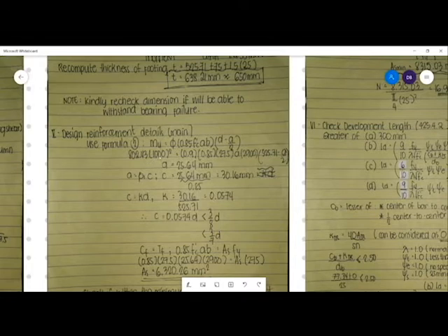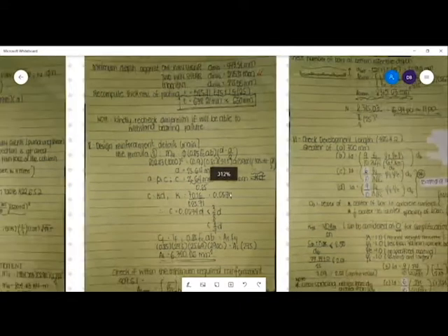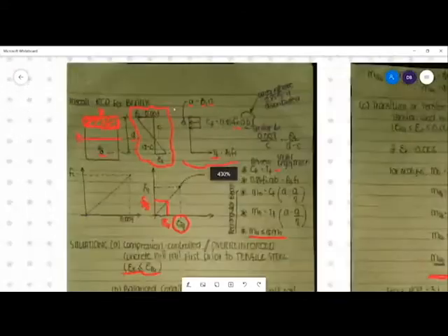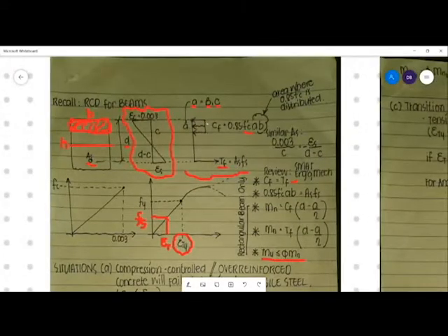We multiply it by 1,000, and another 1,000 to make it Newton millimeter. Then, equal to 0.9 multiplied by 0.85, 27.5 a, 2,900 multiplied by 525.71 minus a over 2. We are able to solve for a as 25.64 millimeter. So that is our a.